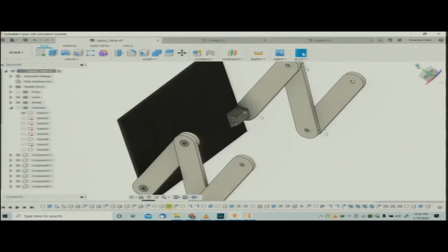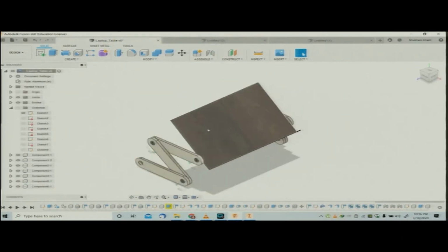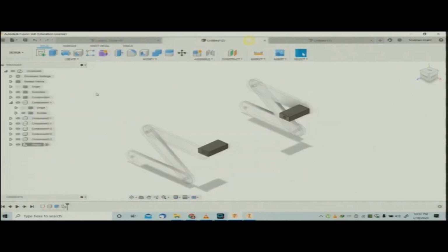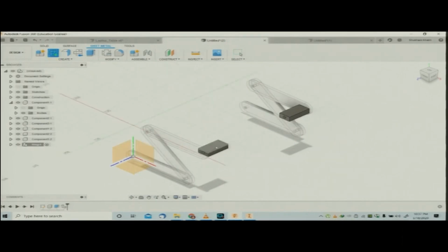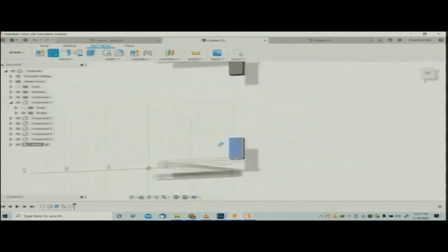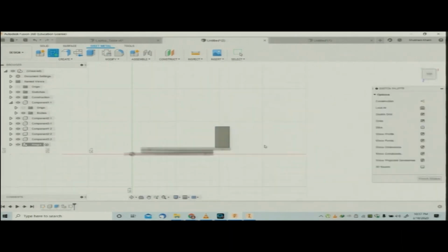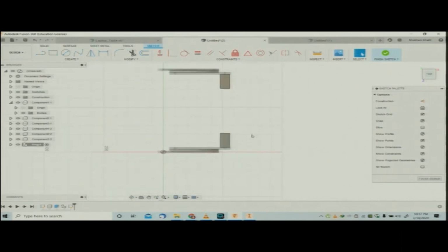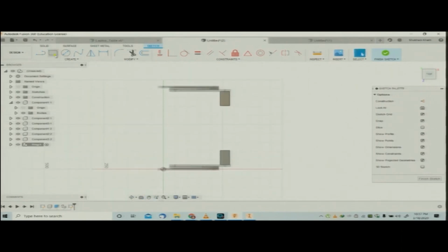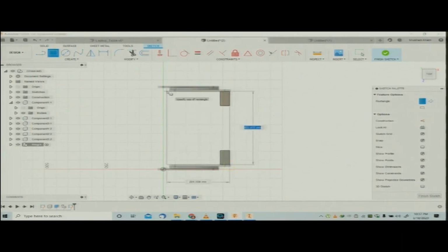Now we will make this top sheet. This is a sheet metal component. So, for this we can select the sheet metal option here. Okay. Now, this is the sheet metal environment. First, we need to make a sketch. Select a sketch here. Then define my plane. Now, I have selected the plane, that is the top surface of my hinge support. We can make our geometry here.